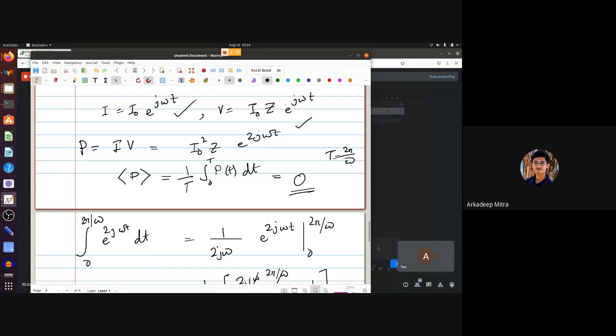Because the differential equations are linear. Well, not just the differential equations. Differential equations is just part of the story. The point is the operations that we are carrying out are linear. That is why real part and imaginary part stay separate. They don't mix up. No problems whatsoever. The trouble here is the moment we multiply current by a voltage, that's no longer a linear operation. You're multiplying two things. And as a result, you're making a mistake right at that point.